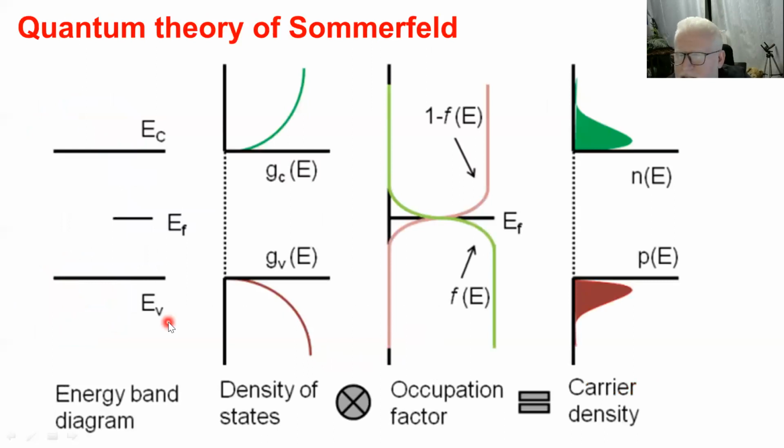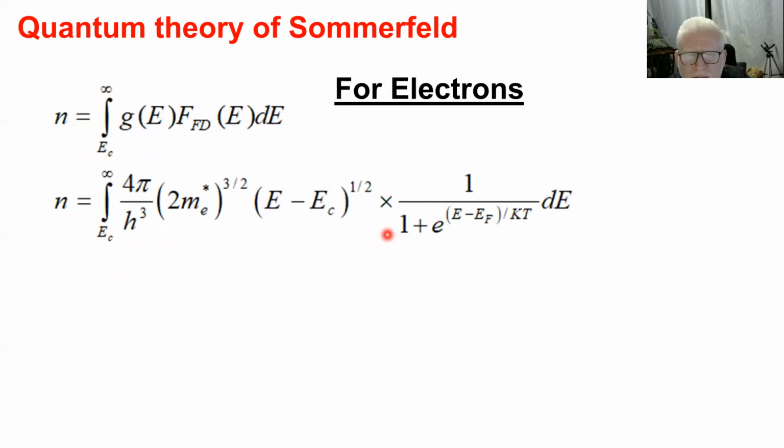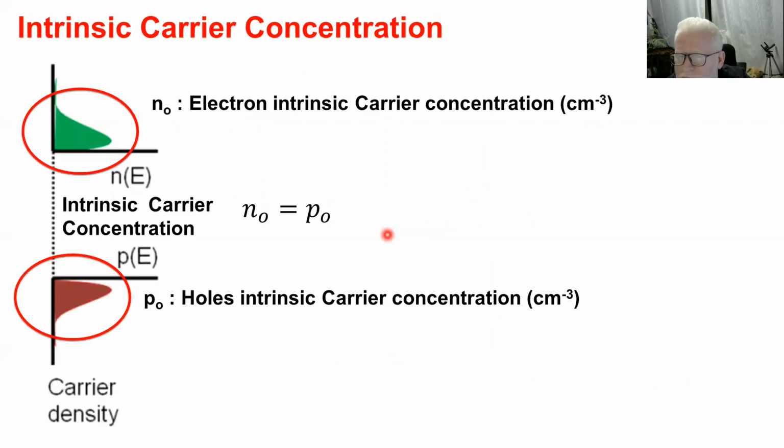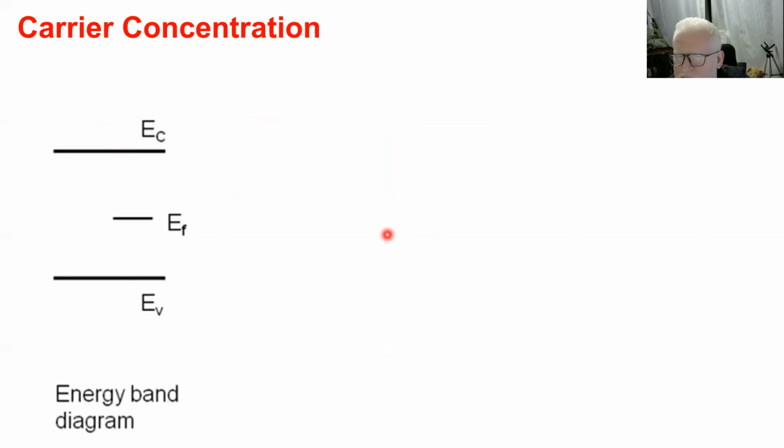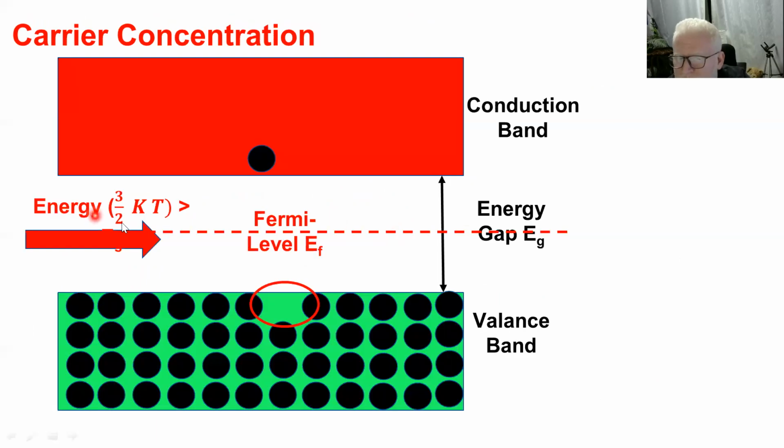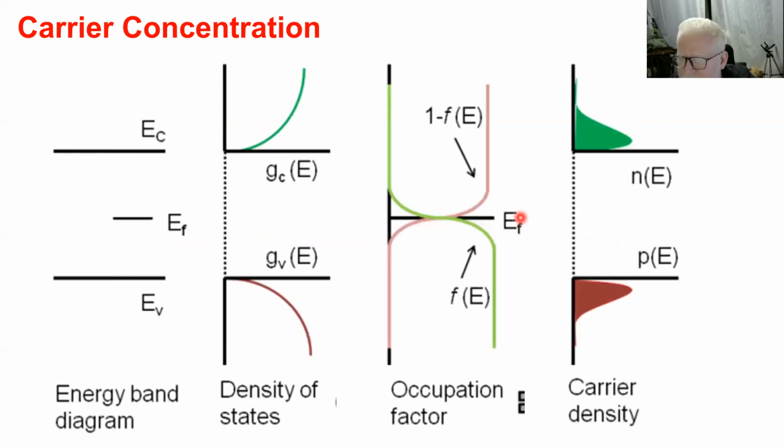Again, this is a very simple multiplication, but now we have to define what I previously mentioned in my first slide in this lecture, which is this reddish line called the Fermi level. What is this Fermi level? Mathematically, this Fermi level is the point at which the probability to find an electron equals the probability to find a hole.